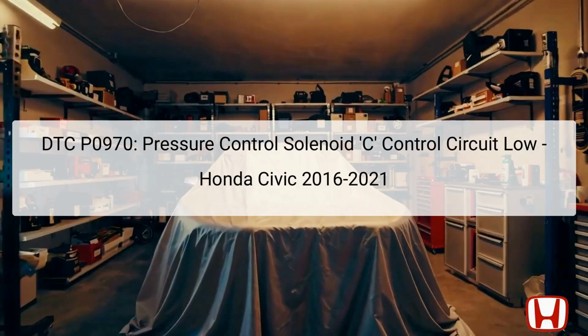The DTC P0970 indicates a malfunction in the Pressure Control Solenoid C control circuit, specifically fitted in the Honda Civic models from 2016 to 2021. This diagnostic trouble code arises when there is a low electrical signal detected in the CVT clutch pressure control solenoid, which is an essential component for controlling hydraulic pressure in the continuously variable transmission, CVT.